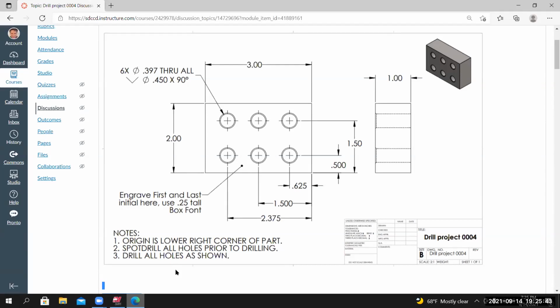Okay. What's going to happen is I'm going to come back in and use the hole tool that's under the Solids tab, and that's going to control the countersink and the diameter of the hole that's going through the part. And then I'm going to create a wireframe representation based off of the solid model that will have both of those diameters included in it.